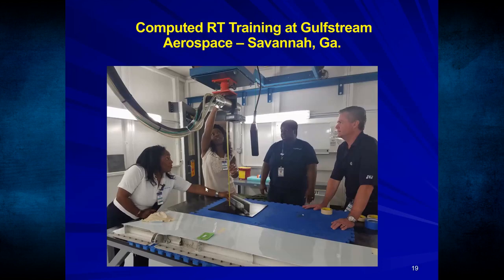So here's an image of me providing training at Gulfstream Aerospace. This is a cassette. Let me just show you with my tool here. Here is the cassette. There's film inside of the cassette. Actually, I believe we're doing computed radiography for this one, so there's an imaging plate inside of this cassette to protect the imaging plate. And this is an airframe spar.